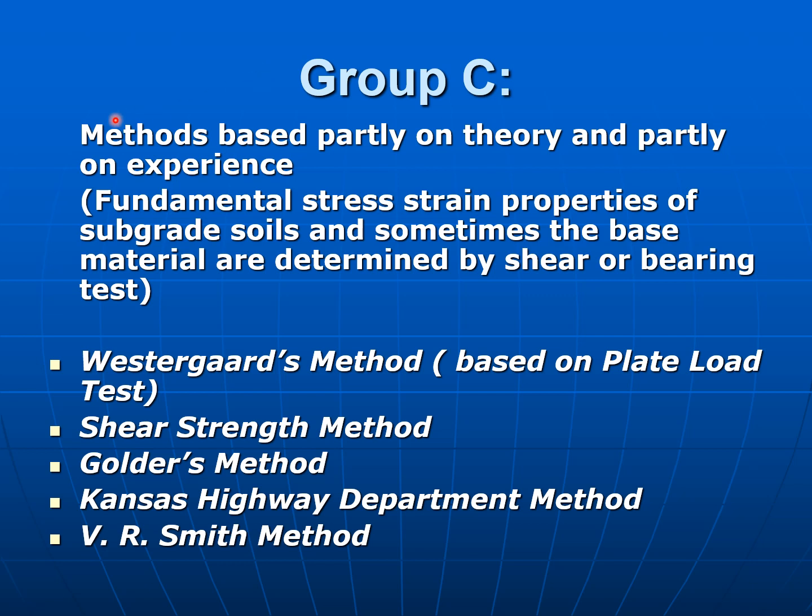Group C. Methods based partly on theory and partly on experience. Fundamental stress-strain properties of subgrade soils and sometimes the base material are determined by shear or bearing test. Under this group we have methods like Westergaard's method, which is based on the plate load test, shear strength method, Golder's method, Kansas Highway Department method, and V.R. Smith method.